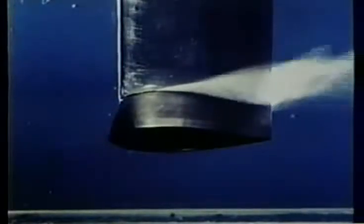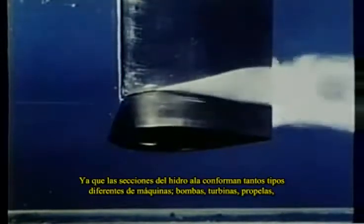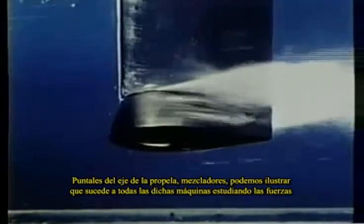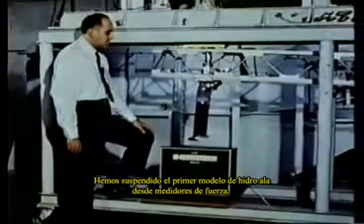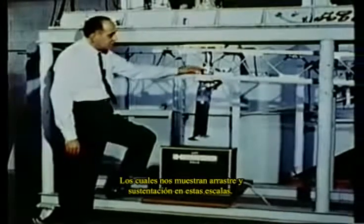Let's turn now to an examination of some of the effects associated with cavitation and cavitating flows. What happens to a machine when it begins to cavitate, and how does performance vary with increasing extent of cavitation? Since hydrofoil sections make up so many different types of machines, pumps, turbines, propellers, propeller shaft struts, mixers, we can illustrate what happens to all such machines by studying the forces on the hydrofoil section itself. We have suspended the first hydrofoil model from force gauges, which show us lift and drag on these scales.